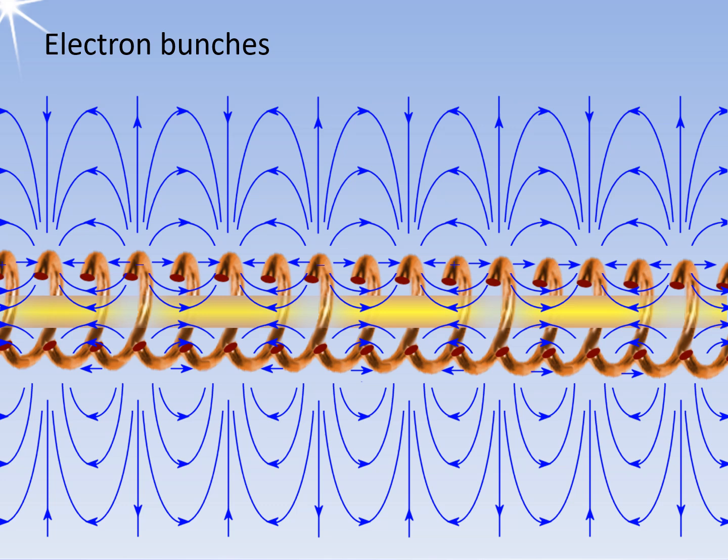The electrons on the helix move at the same speed as the bunches in the beam. In relation to a moving bunch, the electrons on the left move to the left at twice the speed of the bunches. This creates a deficiency of electrons, making the circuit positive. Concerning the moving bunch, the electrons on the right, which are moving at almost the same speed as the bunch, are nearly standing still. As a result, electrons gather in front of the bunches, creating a negative charge in the circuit.